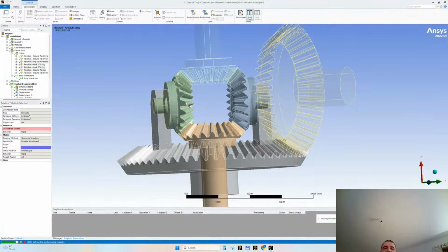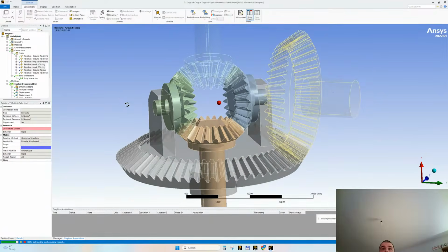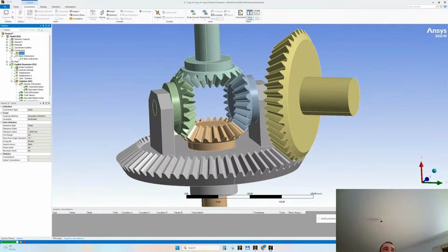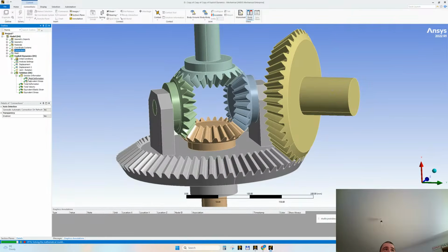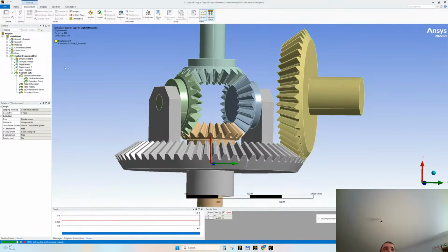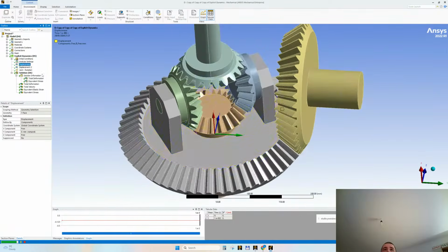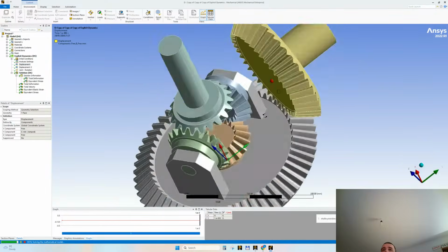We have proper contacts because I have left some gaps in the holes, shaft and holes, and also with the touching surfaces. Keep this in mind in explicit dynamics. Leave gaps because in reality nothing is 0 over 0. Yes, there are gaps in reality. There are allowances. I also kind of restricted some faces. Yeah, here and also here.